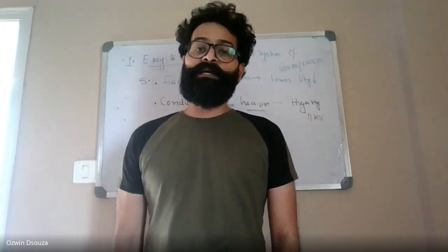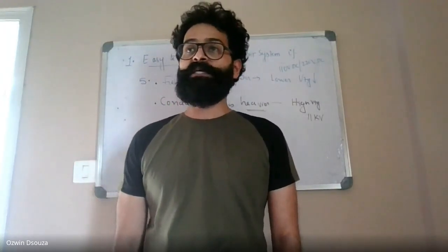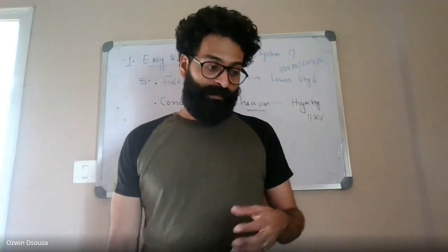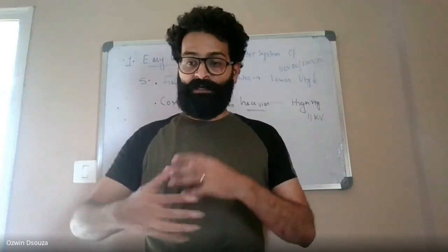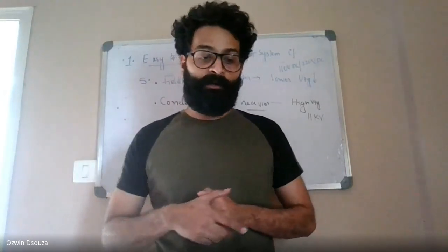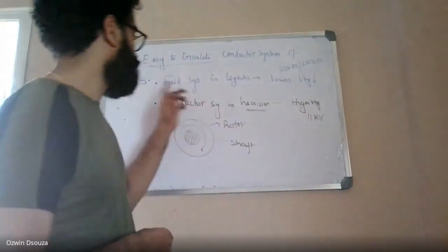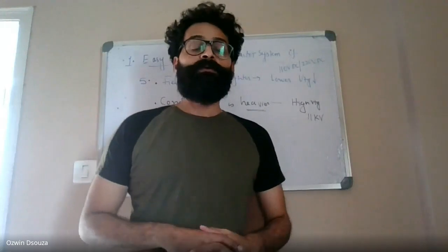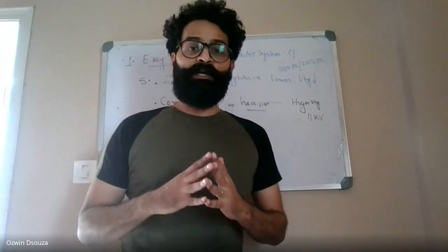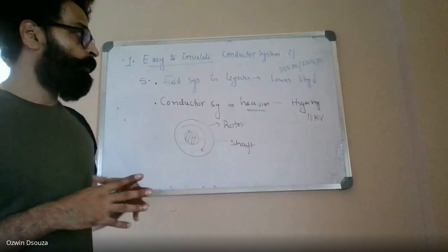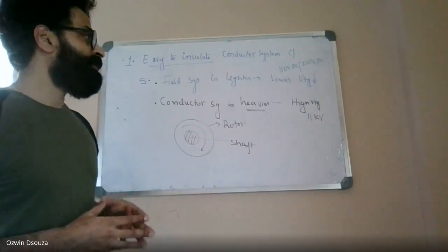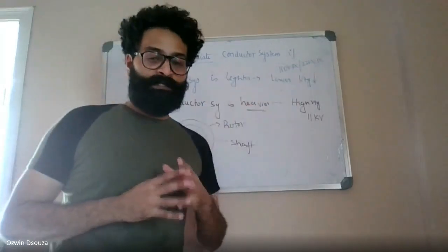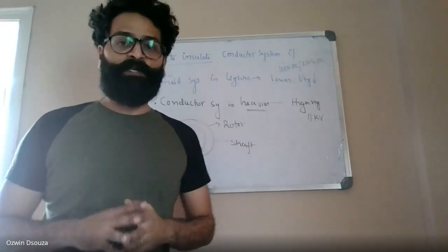And due to these mechanical stresses, eventually the conductors may come out of the surface and can touch the stator part, which is very, very dangerous because your conductor system is working at 11 kilovolts of electricity. So keeping safety as the prime concern, it is always advisable to keep a lighter and lower voltage system onto the rotating part of the machine.